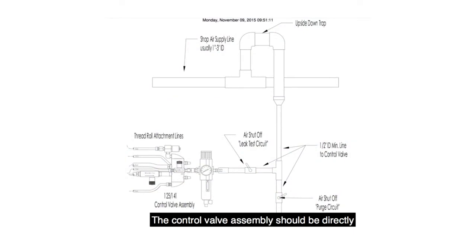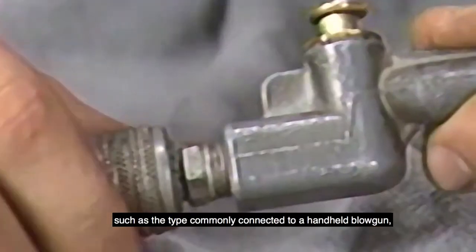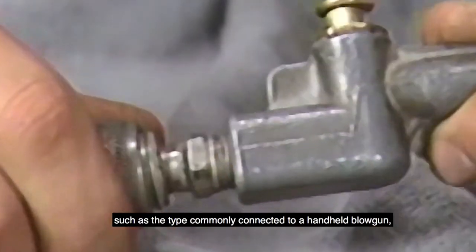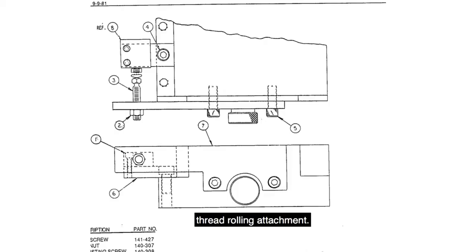The control valve assembly should be directly connected to the main supply line by means of a minimum ID feed line of 1/2 inch. A smaller ID flexible plastic or rubber feed line, such as the type commonly connected to a handheld blowgun, will diminish the rolling pressure capacity of the thread rolling attachment.